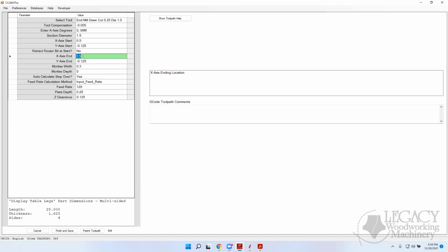Awesome. Great. So is that going to cut the whole depth straight across at 3.5 inches? It's going to cut it 3 inches long, and it's going to do it in a pass depth right down here. We've got 0.25, that's the default. So it's going to make one pass at a quarter of an inch, then it's going to go down another quarter of an inch, as many passes as it needs, a quarter inch at a time, and that's controlled by the pass depth.